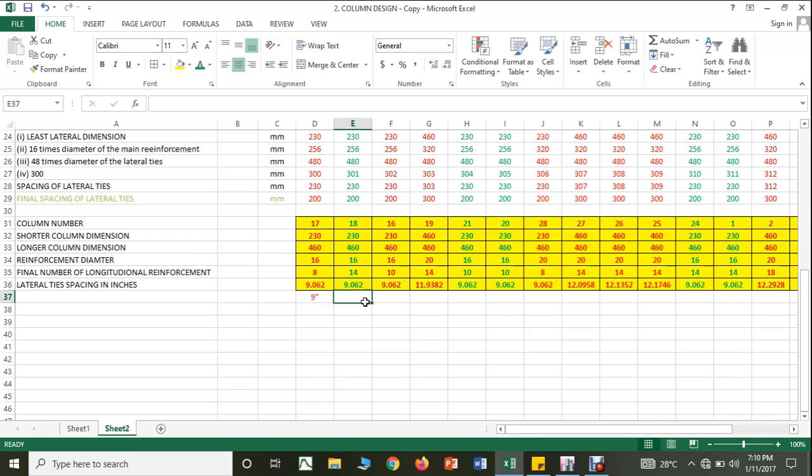But if you are choosing different diameters, that is, larger reinforcement at the corners and smaller reinforcement in the middle, you should make sure that the percentage of steel you obtained in the calculation matches. For example, you are considering a 16 mm diameter rod and your area of steel is something around 3100, and when you calculate, you come to know that you need 12 number of rods.